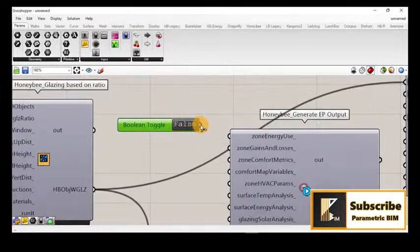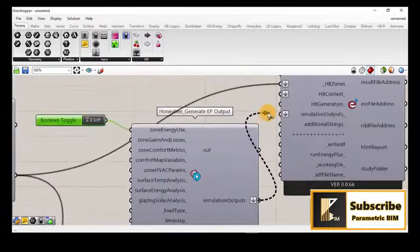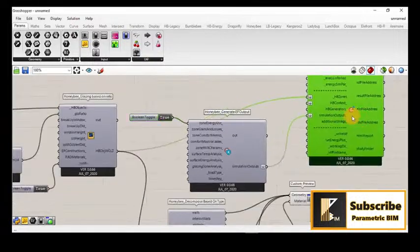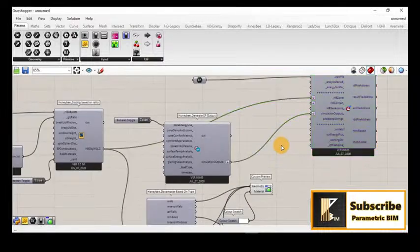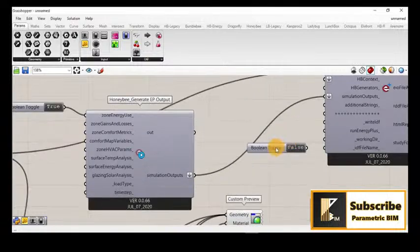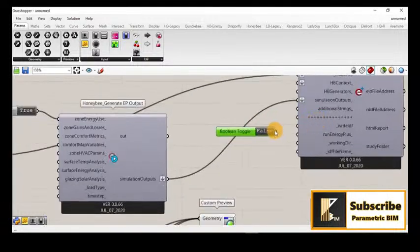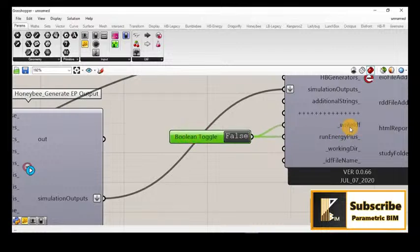I will connect this boolean toggle to the zone energy use, double click, and then connect the simulation output to the simulation output in the Energy Plus. Maybe we are ready now, but we also have to run this energy simulation. So I want to give here the run Energy Plus and also the write IDF in order to have the results in your file.